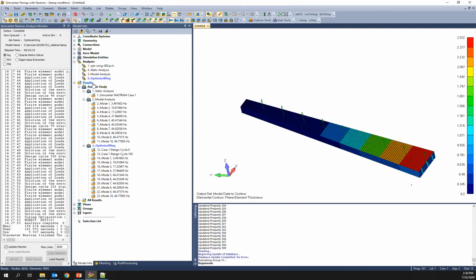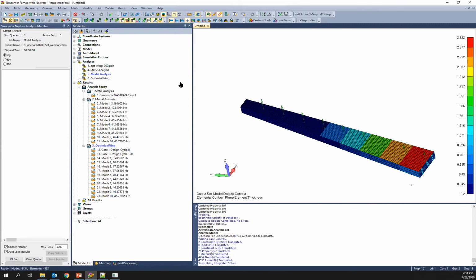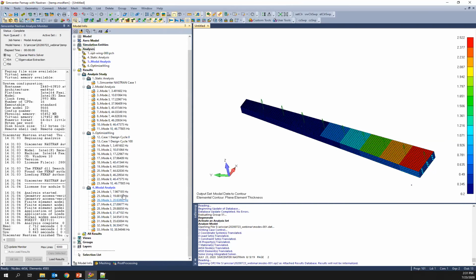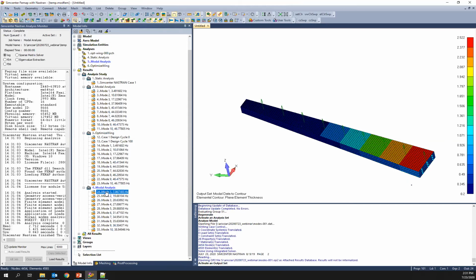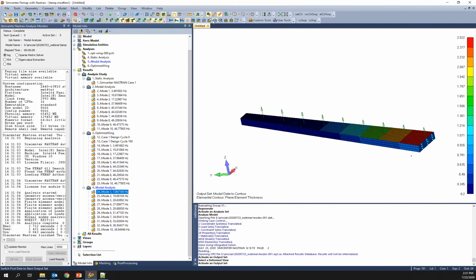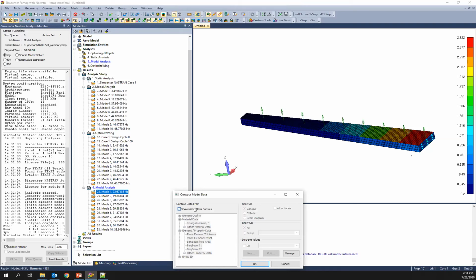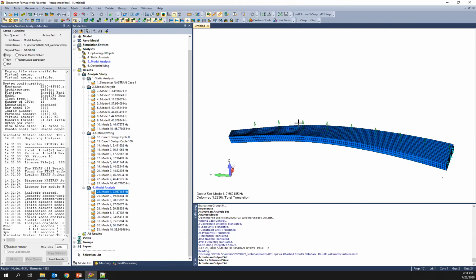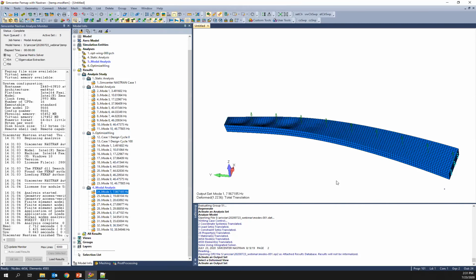So now that we've updated the model, let's just rerun modes. And I want to make sure that that modal frequency constraint is active. So it is. If you remember, that was an 8 Hertz modal frequency constraint, and we're about 8 Hertz and some tolerance that Nastran used there. Oh, and I need to turn this thickness off to see the displacement result. So that's our first mode. So all that material got added to drive this frequency up to 8 Hertz. So that's the only active